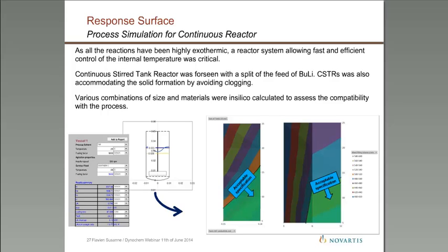And we can screen all these parameters specific to the characteristic of the reactor. And actually we can see that, based on impurity 1 and 3, we have some acceptable range here. Based on this acceptable range, we can define which type of reactor is suitable for the chemistry to hold this set point. Like that, we are not blindly thinking that we know about the chemistry and hoping for the best that the reactor will suit our need. We are able upfront to put into relation the chemistry and the reactor.